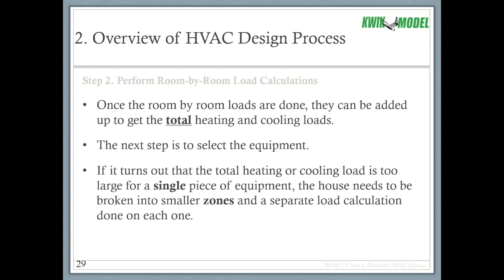A very common example of that is larger two-story homes. The total load of the house might be too big for a 5-ton piece of equipment, so they will split it between upstairs and downstairs, with an upstairs block load and a downstairs block load, and you'll have two separate pieces of equipment to handle those two zones.